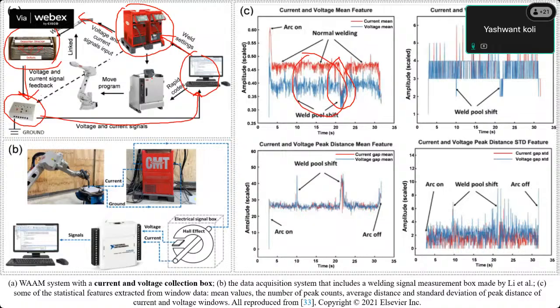If the voltage signal shows irregular patterns or missing segments corresponding to the pore locations and sizes, we can conclude that there is some porosity in the fabricated part. So these two things are important. First, the voltage parameter relationship is distorted, and second, the irregular patterns of the voltage. If these are showing, then we can tell that the fabricated part has a porosity problem.